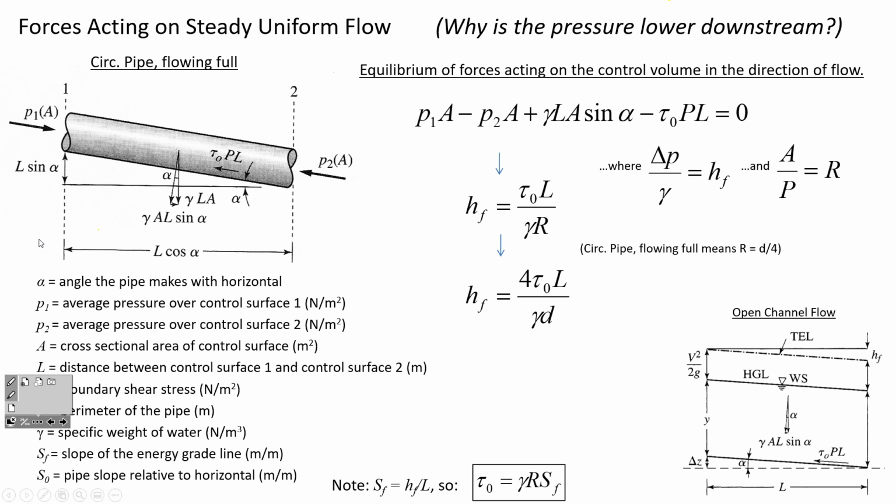All of this that I've showed you so far has been for a pipe that is enclosed, where the water is inside a circular conduit. If you have open channel flow, meaning it's water going through a river and it's not pressurized, then there are similar considerations. We've got the energy grade line. Here they're referring to TEL, meaning total energy line.